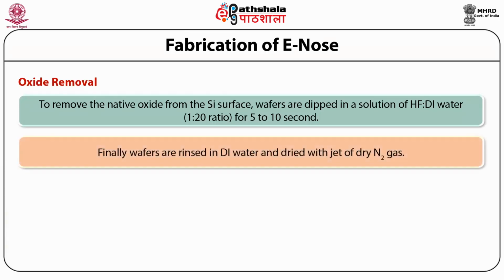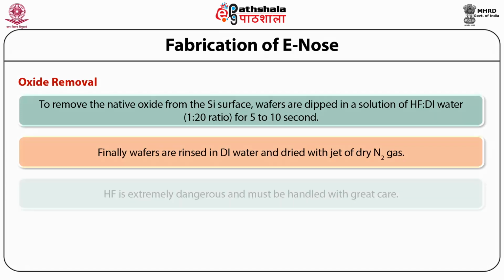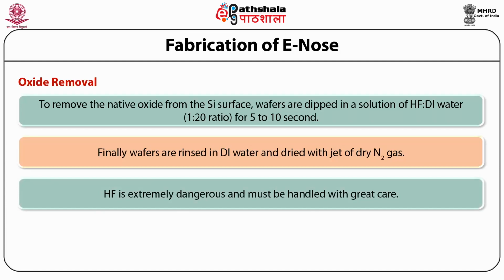Finally, wafers are rinsed in DI water and dried with a jet of dry nitrogen gas. Now, HF is extremely dangerous and must be handled with great care.